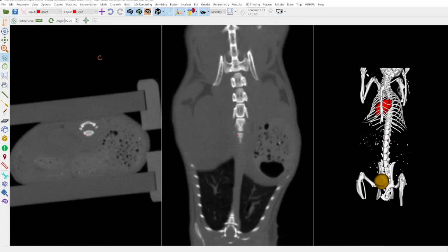But now I will explain the buttons on the top here. Again, you can hide the scribbles with this box. When you go to the eraser, you delete the scribbles. So when you start a new segmentation, I always recommend to press F1 first to delete scribbles, because sometimes by coincidence, if you click somewhere, you can draw some scribbles and maybe you didn't want to draw them at this position.